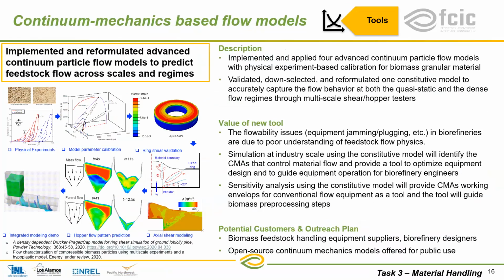Let's talk again about the CFD, or the continuum mechanics. So the researchers on the material handling task looked at 4 different continuum particle flow models, these constitutive models, if you will, to put them into a CFD model and then validated against some experimental work. Again, the CFD models are easier to solve than the DEM models, but they do require a good constitutive model. That's what this work helped provide. This work will be offered for public use.